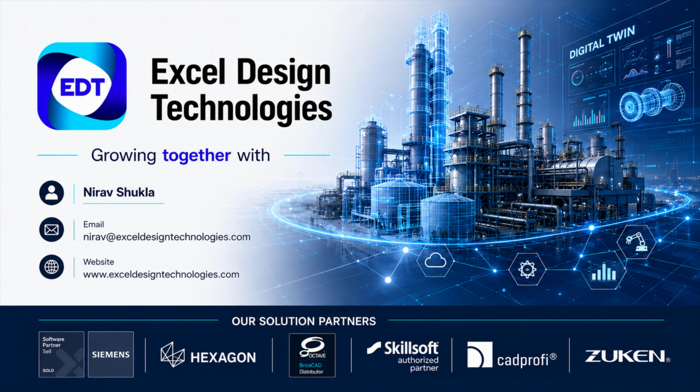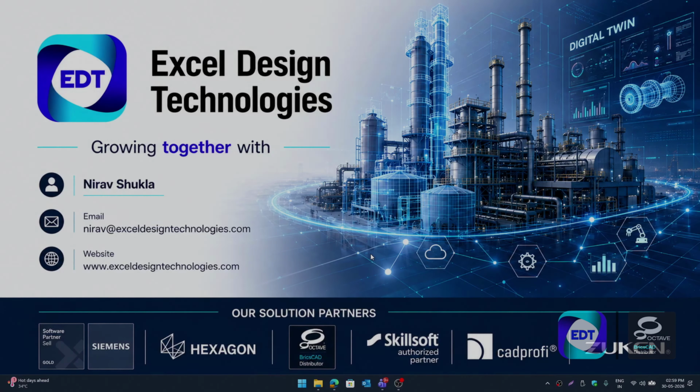Have you ever received a STEP, IGES, Parasolid or SolidWorks file and wondered how you are supposed to open this inside BricsCAD? Well, don't worry, because BricsCAD Communicator is here to save the day. In today's video I'll show you the complete process of downloading the BricsCAD Communicator, installing it, activating the license and finally importing a real 3D CAD model into BricsCAD. So let's jump right in.